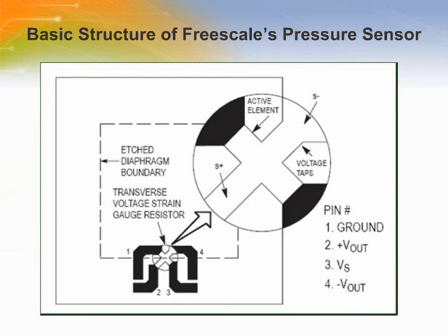Unlike conventional pressure sensors, which utilize four closely matched resistors in a distributed Wheatstone bridge configuration, Freescale's pressure sensor is designed utilizing a monolithic silicon piezoresistor, which generates a changing output voltage with variations in applied pressure. The resistive element, which constitutes a strain gauge, is ion implanted on a thin silicon diaphragm. Applying pressure to the diaphragm results in a resistance change in the strain gauge, which in turn causes a change in the output voltage in direct proportion to the applied pressure.